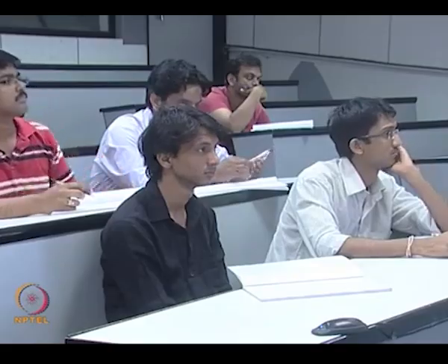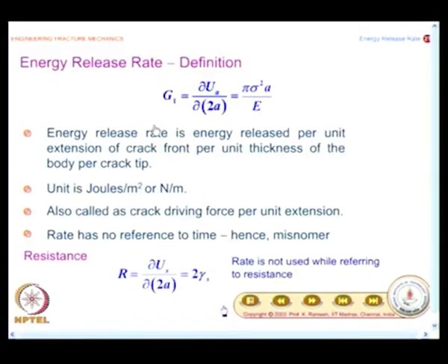The length of the crack also plays a role. That was a key contribution by Griffith. And another aspect what you will have to look at is, we have done an energy balance. We have also said for the formation of two new surfaces I need energy, and this energy comes from the strain energy of the system, and the resistance is inherent to the material.